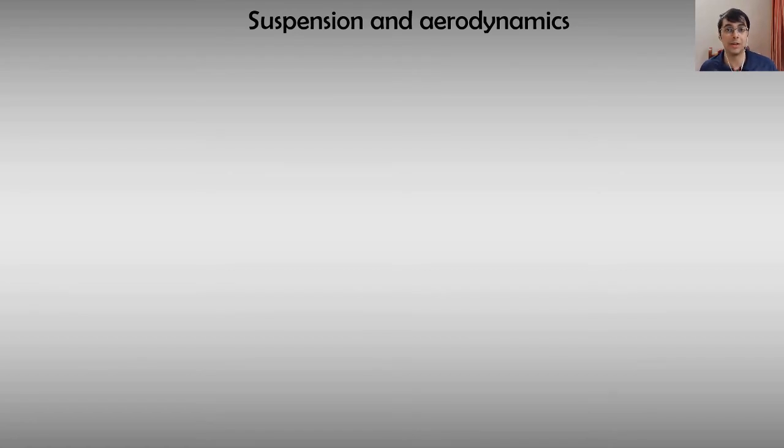Right, so hopefully that video was helpful and it helped you understand the differences between oversteer and understeer for different cars based on the wing angles. So something else to remember is you can get more downforce in the front if your front wing angle is higher than the rear. Not exactly numerically true. Basically, by increasing the front wing angle, you can get more downforce, but it depends on the design of the car to choose the right angle.